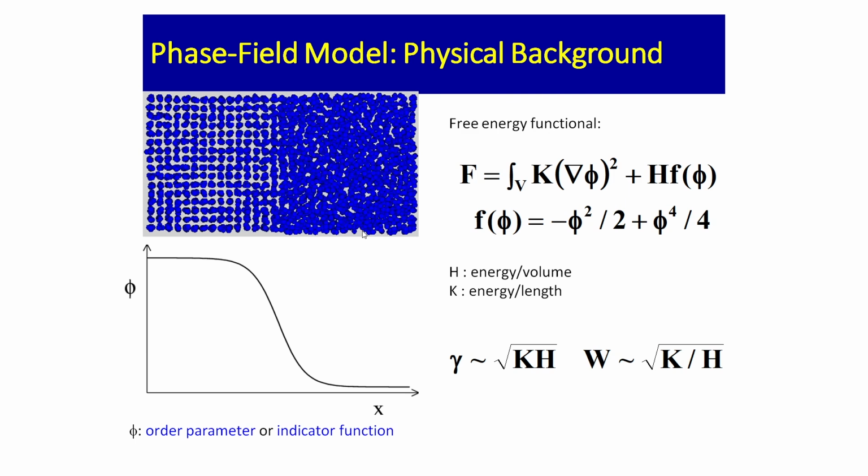So, now how do you characterize the interface? We will talk about these equations now. In the phase field model, the state of the entire microstructure is represented by one continuously varying single variable, because we have to develop one single partial differential equation, and you have free energy of the phases and surface energy of the interfaces. So, what do you do? You cannot have different sets of equations, then you have the problem of tracking the interface. So, the entire microstructure is represented by a single variable.